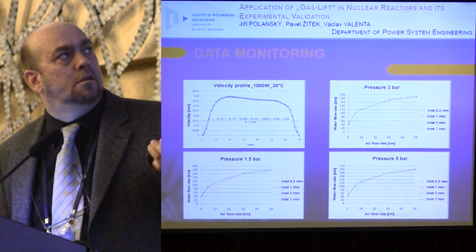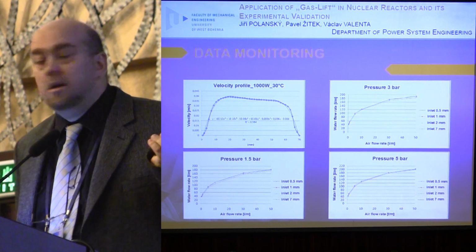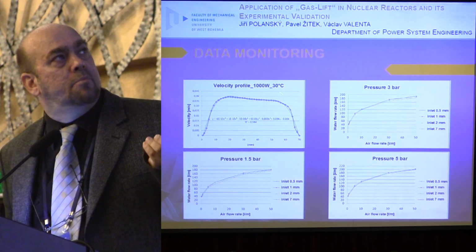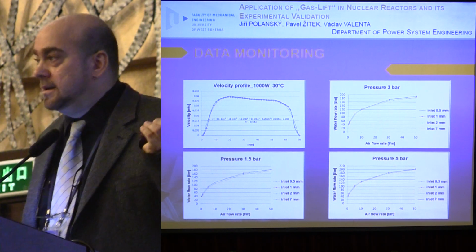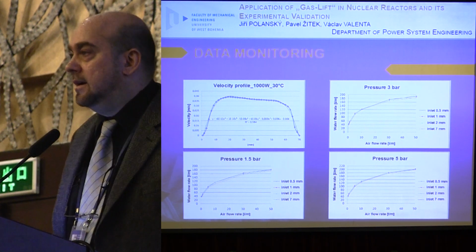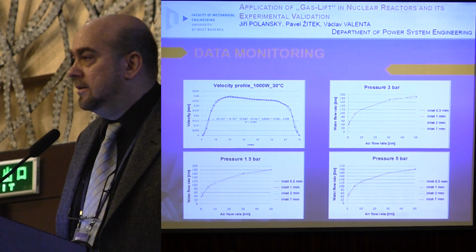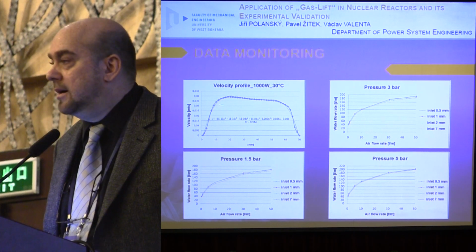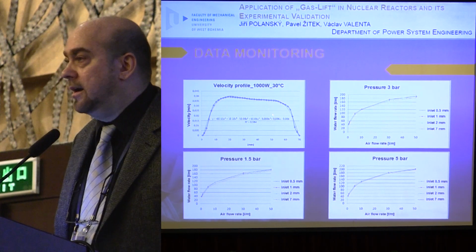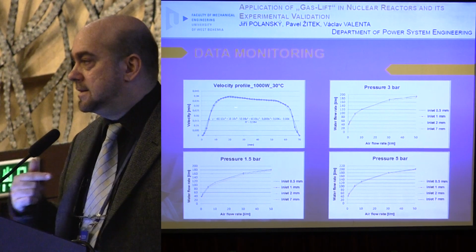Maybe a little comment on the velocity profile. You can see that we have a problem with the symmetry, and in fact this picture shows that our distribution of the gas is not perfect, and we deform the velocity profile. It was information for us that we have to improve the gas input.